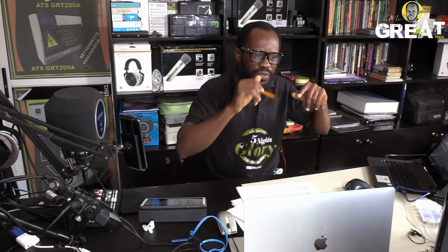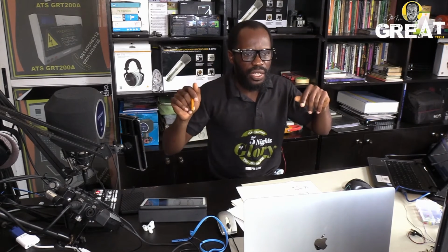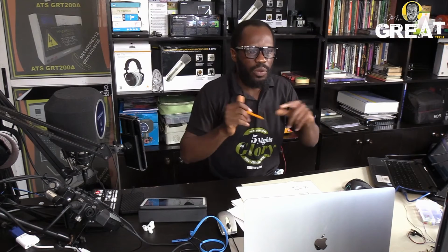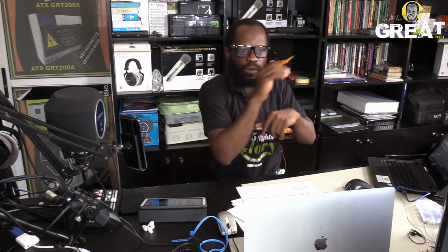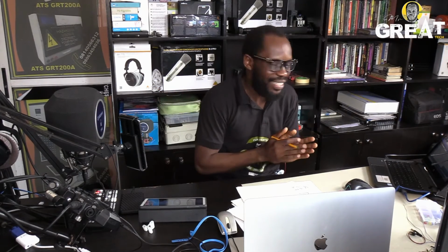So you do your cross multiplication. If I have 0, it equals 0. And I have 5 volts, it equals 1023. So if I have 3 volts, it will equal X. So I do cross multiplication, then I get my X on the Arduino scale. So now I have a scale. Then I have to get the voltage, in the same way.